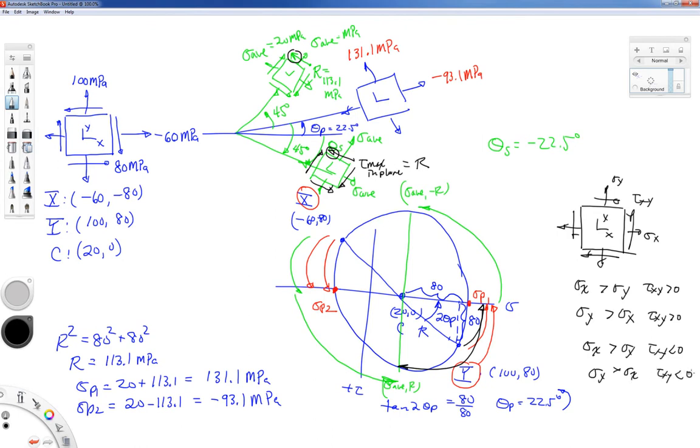If you put in numbers and do all of those four combinations, there are no problems that I could give you on a test that you haven't already gone through the procedure. All this does, by changing the magnitudes and signs of these normal and shearing stresses, is put your x point and your y point in different spots on the circle. Sometimes they could be here, here's the y, and here's the x. Sometimes they could be here's the y, and here's the x. It just depends on how those shape up.